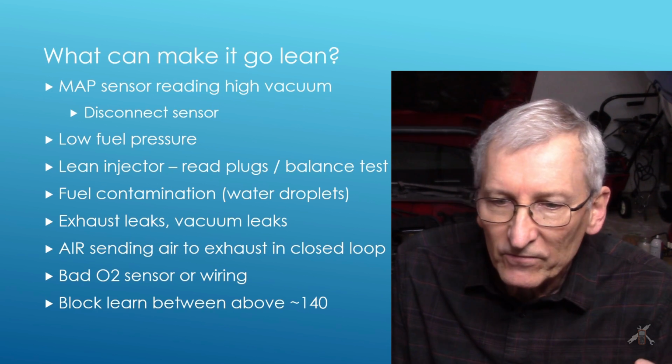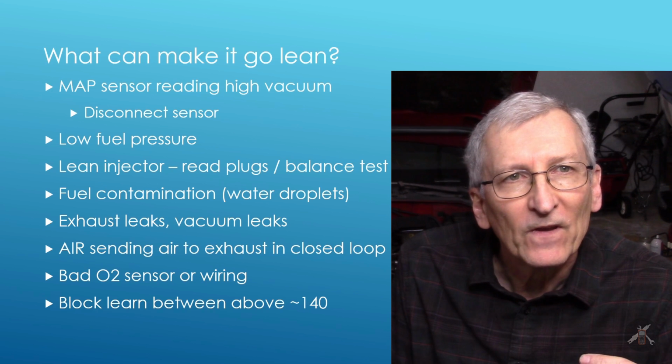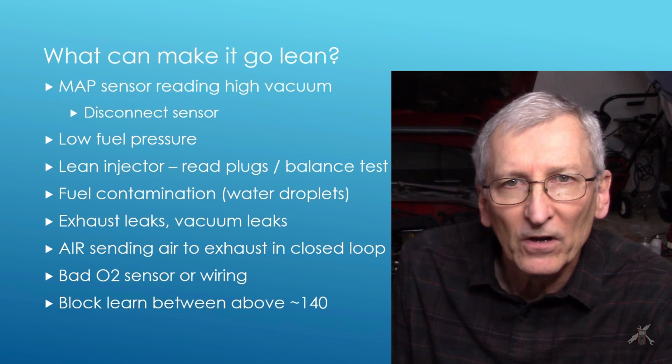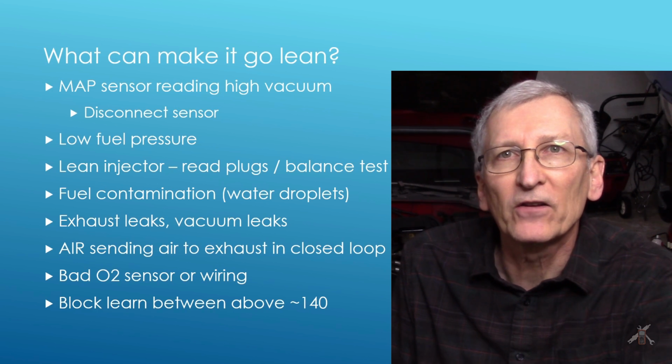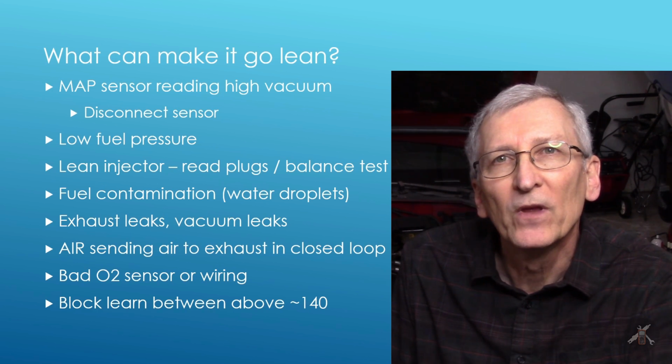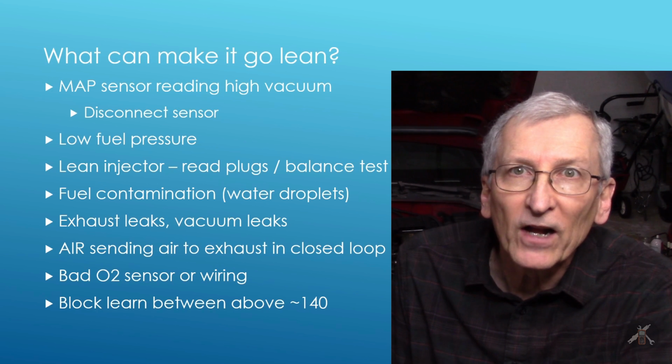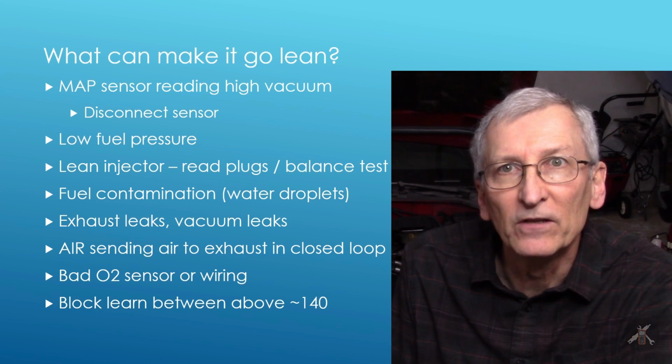Exhaust leaks, vacuum leaks. Vacuum leaks affect the way the engine runs. Exhaust leaks will affect air in your exhaust system, which will affect your oxygen sensor and cause it to read lean.